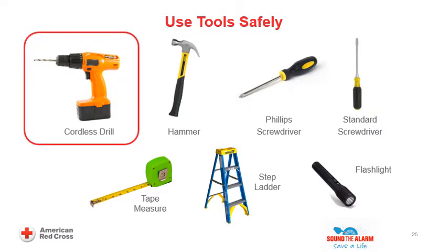Cordless drill safety overview. Guidance adapted from Portable Power Drill Safety. Pre-use activities. Thoroughly review and understand information provided in the operator's manual, with particular attention given to descriptions of safety procedures. Before using, always inspect the cordless drill for damage or disrepair. In addition, assure that the drill chuck is functioning. Also, properly inspect the battery pack as appropriate. If the cordless drill fails your inspection, notify your event leadership and remove the cordless drill from service.